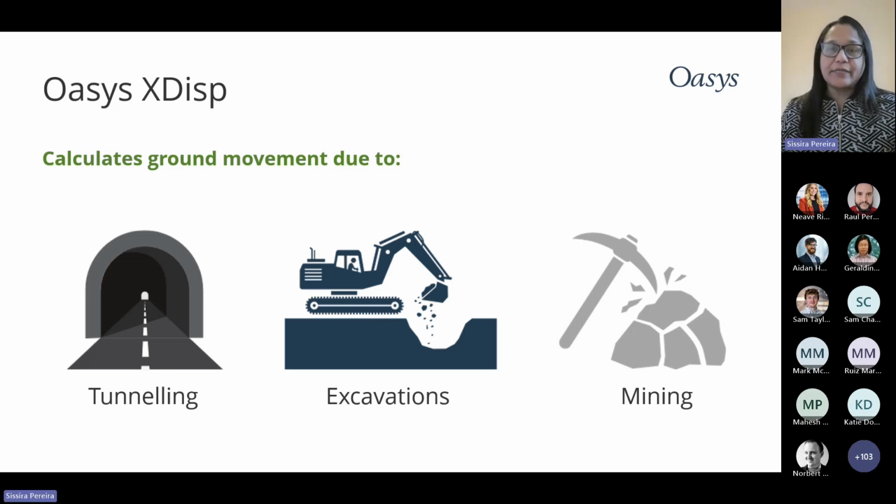For embedded wall excavations, these are described in plan as polygons with a level at each corner or as circles with a single base level. Each wall of a polygonal excavation and each circular excavation is assigned horizontal and vertical ground movement curves that are then used to calculate soil displacements. Settlements and horizontal ground displacements can also be calculated. Graphical and tabular outputs are available.